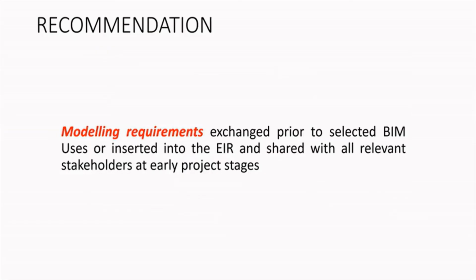So in a nutshell, these modeling requirements are exchanged with selected BIM users prior to being inserted into the EIR. Once you have the documents, you know what the design authoring team can and cannot do, so you put only the ones that the design authoring team can do as a requirement to design authoring, and you put the ones that the other BIM users have to do themselves.